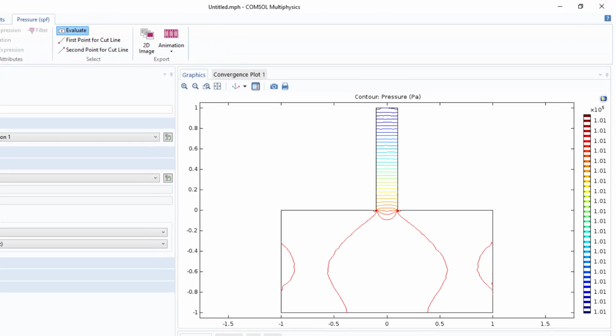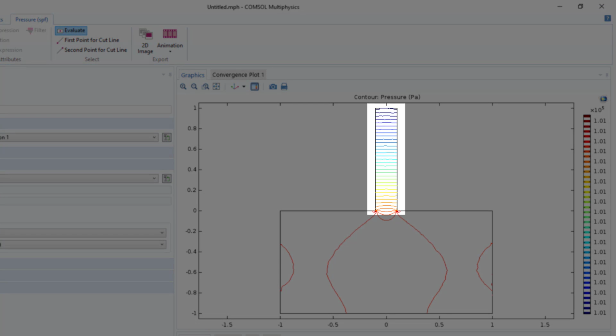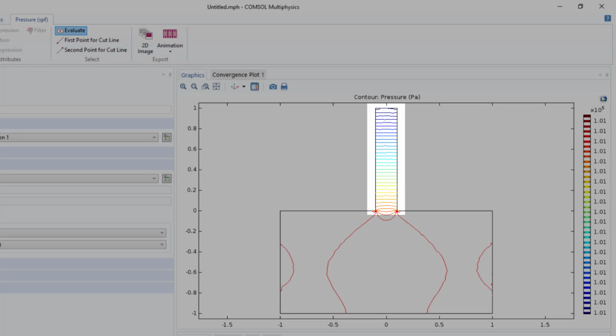Here we can see that the pressure drop through the narrow gap is very linear, equally spaced lines, and also nearly perfectly flat in the x direction. That is, the pressure in the narrow gap drops linearly with increasing y, and is not a function of x. This verifies the assumption that we make in the Navier-Stokes equation that dp/dx is equal to 0.